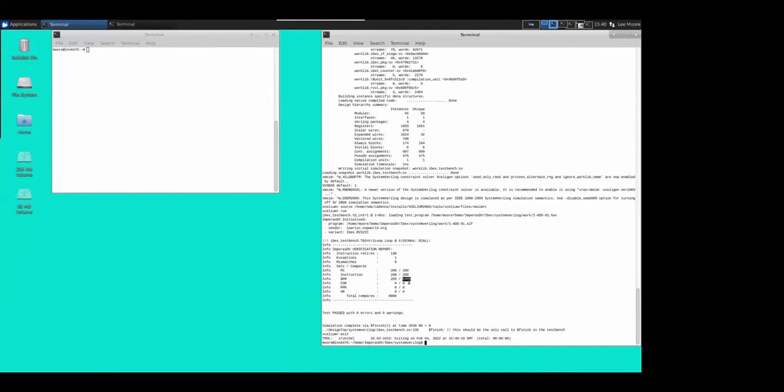The reason why we have 6,400 comparisons here is because, of course, there are 32 GPRs, and not only do we check for GPRs that get set, we also look for side effects for ones that we ensure have not been set. So ultimately, running this tells us we have 6,800 comparisons and we've had no difference. I sometimes liken this environment to having a very smart assertion checker in your code, that in general you expect to be silent, but when something goes wrong, you want it to raise a flag and tell you that there's a problem.